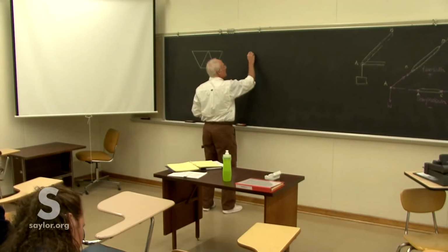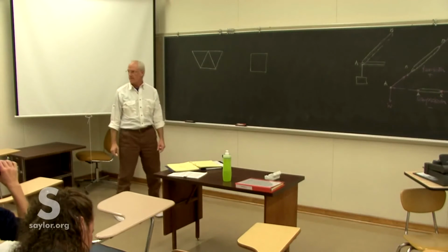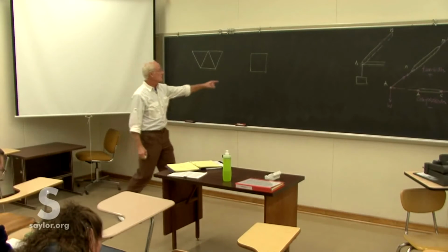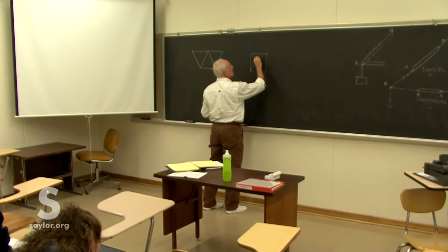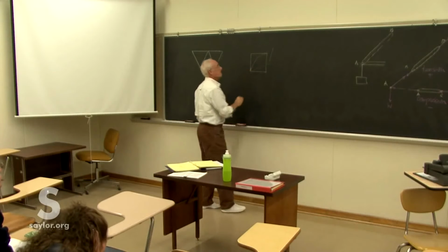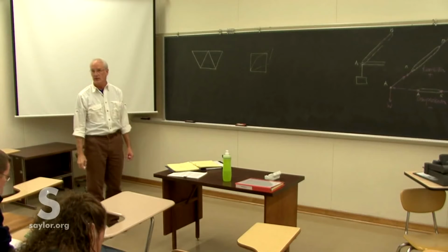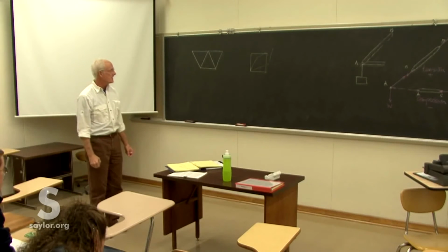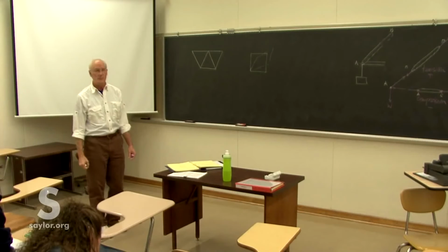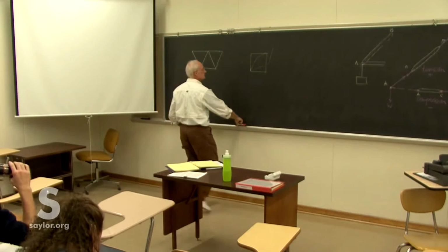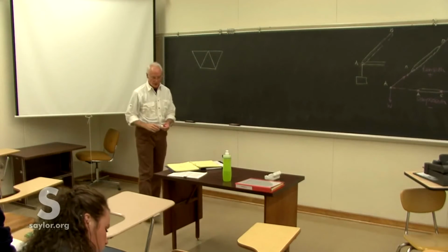If we had part of a truss that looked like that, remember the joints are freely pinned and they can turn, which means that this could collapse and then the structure itself would fail even if there's no material failure. So we can't have any squares or shapes beyond that, any polygons above a triangle. That doesn't mean we don't have some design options as we go through this.